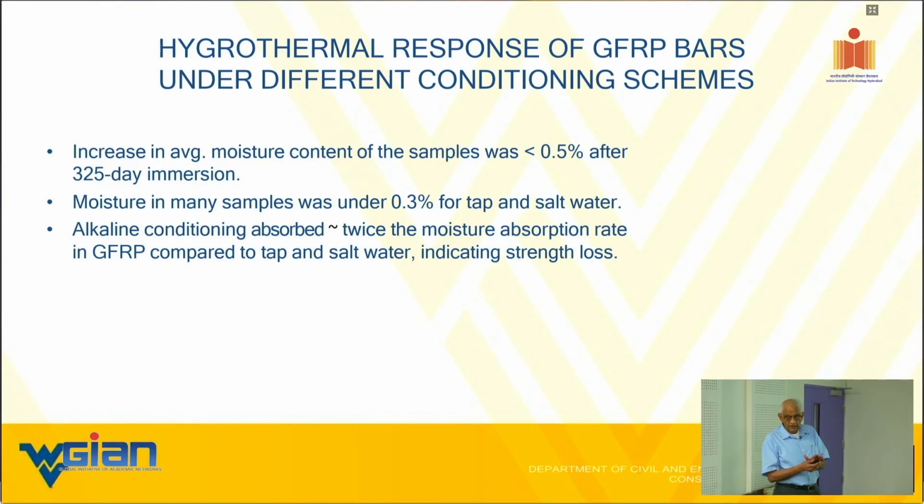But you need to protect that bar with a compression molding using polyurethane type. Again, I have all that nitty-gritty information in this 300-page report. Somebody, when I go back home, I can send that report, you know. All that info is there, including how we have conducted the Arrhenius equation. There you have the degradation rates of bars as well as the bars in concrete for 3 to 5 years.